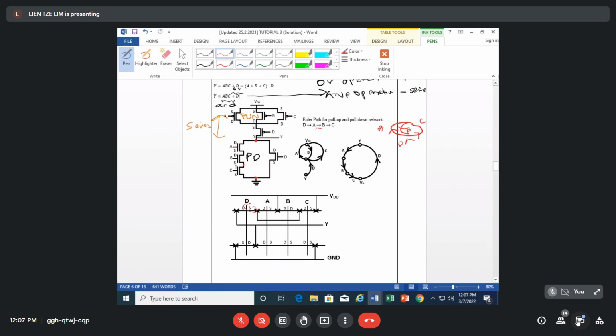If you determine here the transistor as drain, it is not correct. It should be source because it is connected to the drain terminal of the transistor with input A. And then here, since this is the source terminal, this will be the drain terminal. After we label all the drain and source terminals, then we can draw the connections.